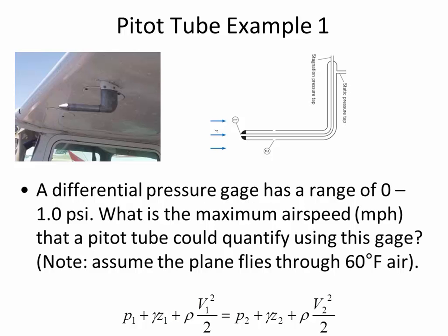That's right. So all of the velocity energy that was there got converted into a little more pressure. And so what we're saying in this problem is let P1 equal 1 pound of force per inch squared, and let P2 equal 0 pounds of force per inch squared. Now maybe it wasn't immediately obvious to you that that's the implication of this problem statement. Sometimes the hard thing isn't Bernoulli's equation, but it's applying Bernoulli's equation to unfamiliar phraseology here.